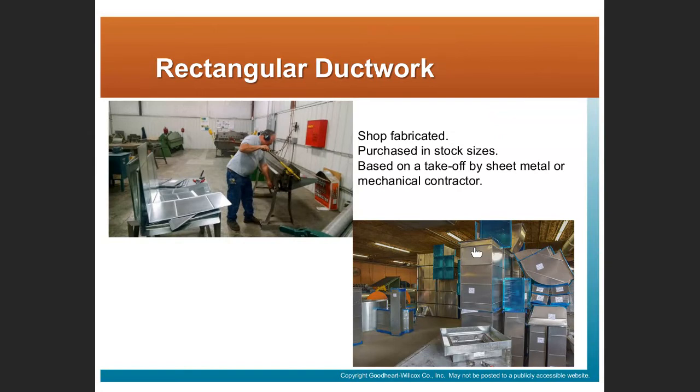So it's typically not welded because the amount of pressure that that ductwork is taking is relatively low, that these strap or cleated connections will handle the pressure requirements. Does that answer your question, Ayana? And I'll see if I can find a better picture of that.